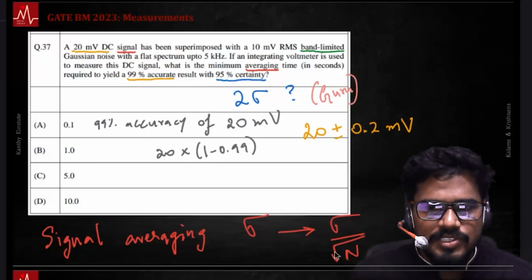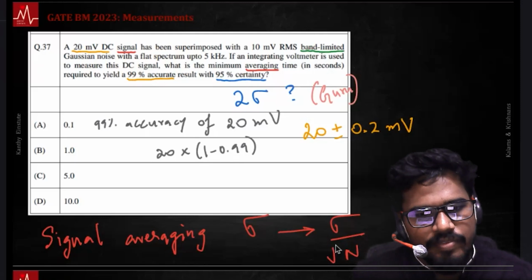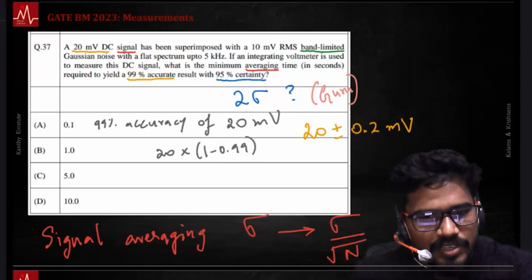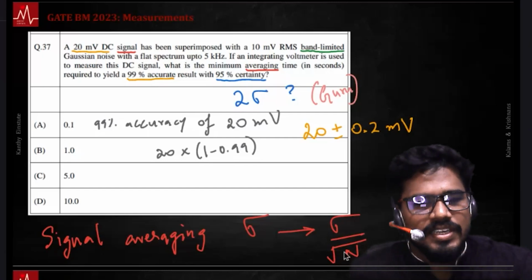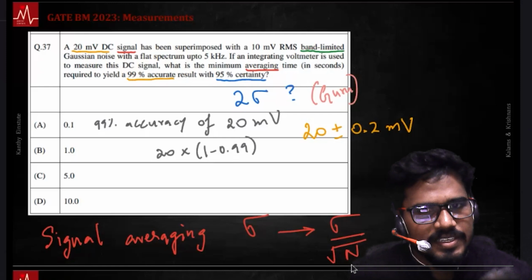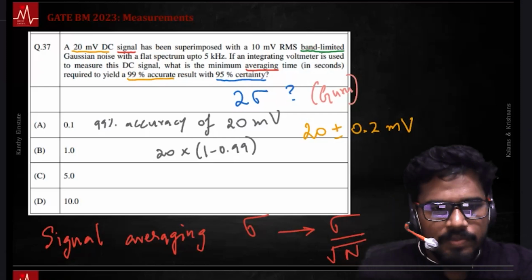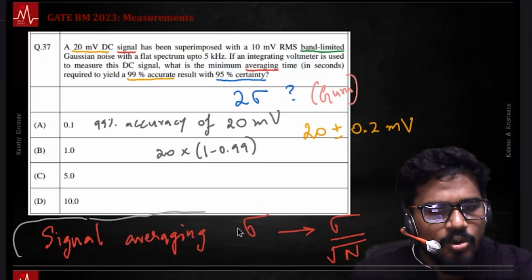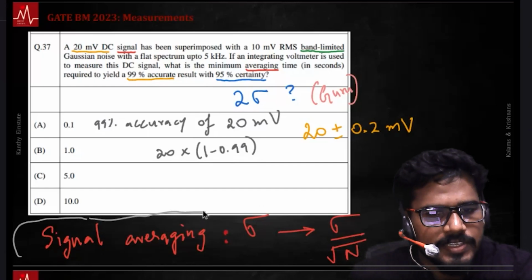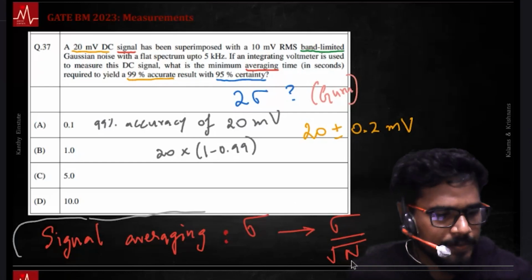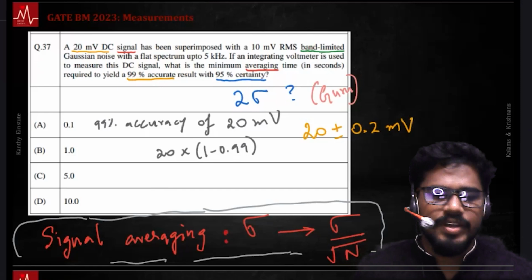That is, the standard deviation characterizes noise. If you use n samples, the noise comes down. Say n is 1, the original noise. If n is, let's say, 4, noise halves, right? Like that. Quick question. Does the statement alone make sense? Signal averaging, the amount of your noise comes down. Standard deviation of your noise decreases if you average n signals. Does this make sense? How much does it decrease? Sigma becomes sigma by root n. Doesn't make sense? If it doesn't make sense, I can quickly